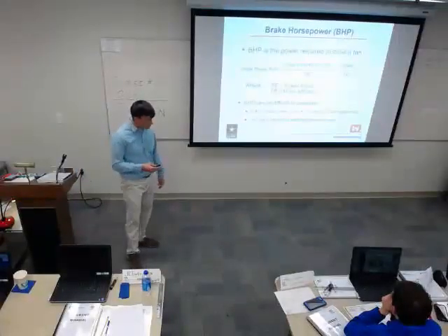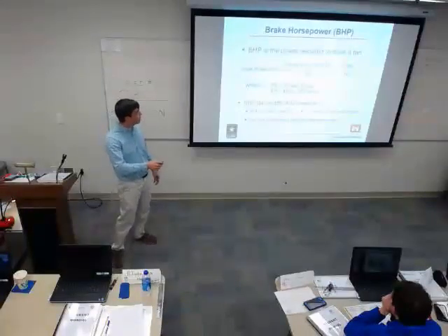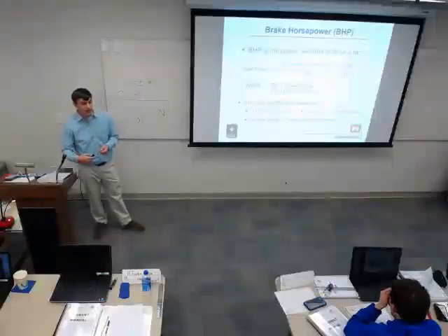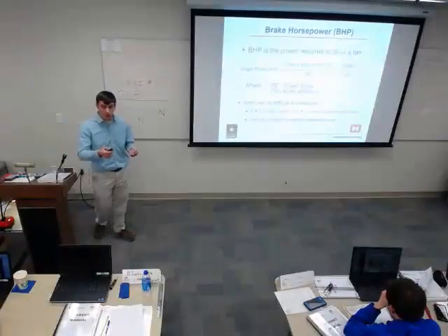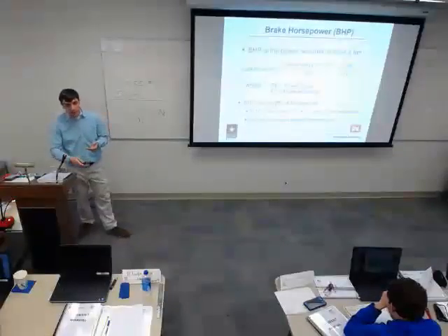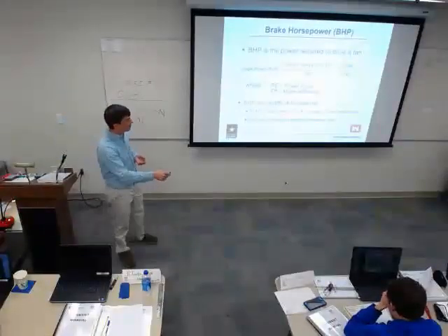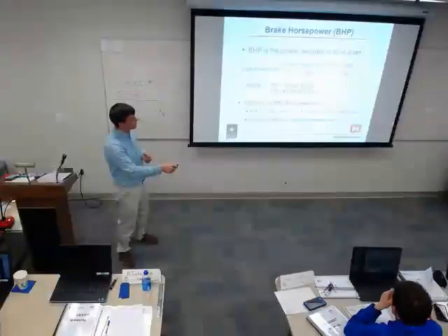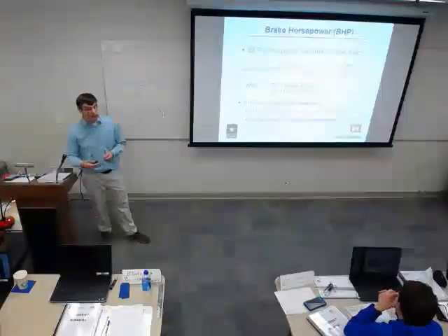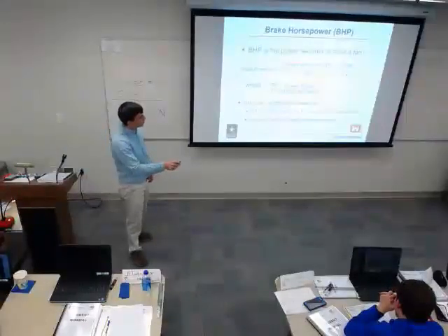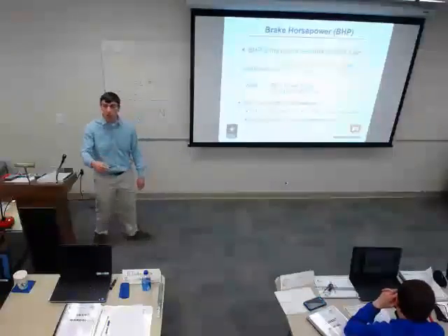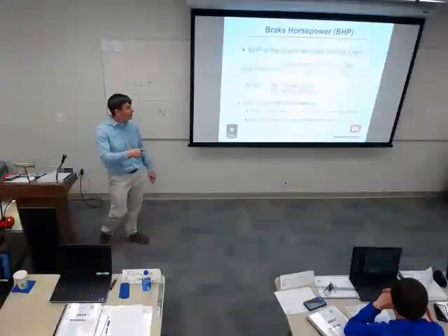Brake horsepower, and this kind of comes into play. If I want to calculate brake horsepower, which is the actual power required to move the fan, when I go measure current and measure voltage, that's on the incoming side of the motor. The motor has an inefficiency in it, and there's a power factor. So I have to put more power into that motor than it actually takes to move the air. And that's where, if I wanted to calculate brake horsepower, I would have to know my power factor, which your standard voltmeter doesn't give you. That harmonics analyzer would have to give you that.